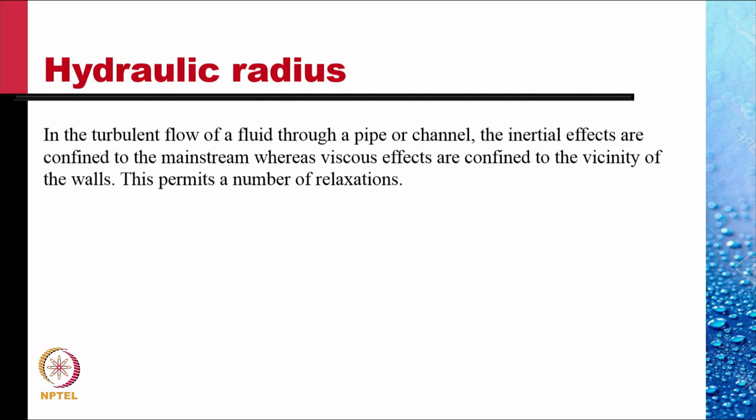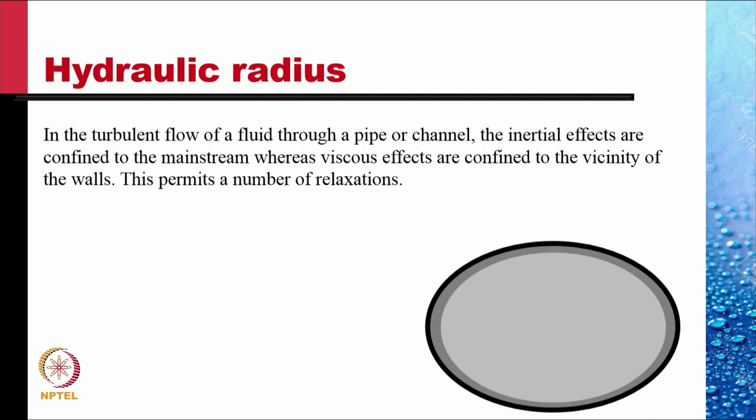In such flows, the inertial effects are confined to the main stream, whereas viscous effects are confined to the vicinity of the walls. Consider this elliptical tube. I drew an elliptical tube because it was easy to draw on a PowerPoint, but it could be a tube of any section.